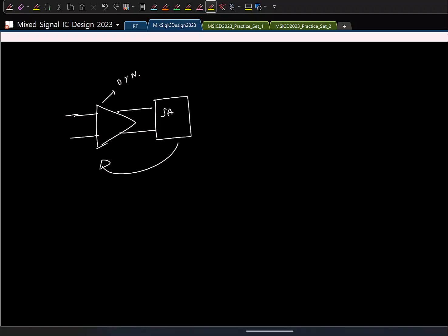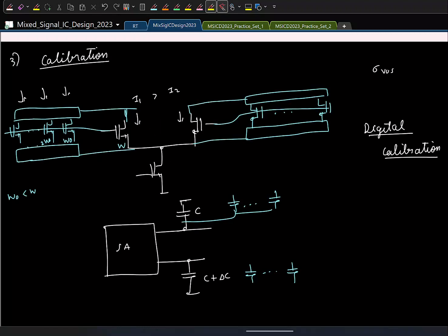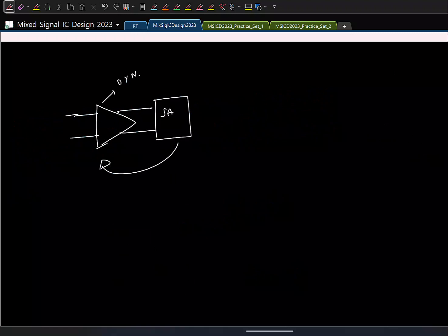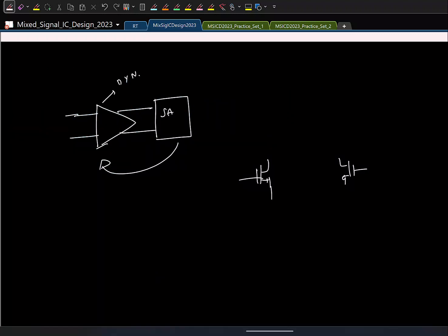Yeah, okay, I understand. So in that case, what you can do is, he's saying if you add transistors here, one side becomes stronger than the other. So the gate capacitance on one side will be larger than the other. That will present asymmetric loads. Like I mentioned, this is not the only way, right? The other way to counter this is, let us say you have this, you don't touch the gate side. Remember that I just want to make these two currents equal, right?